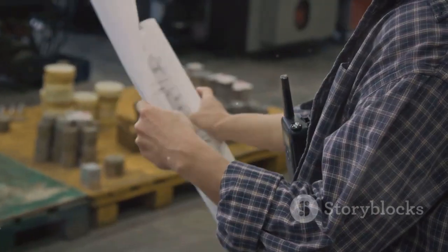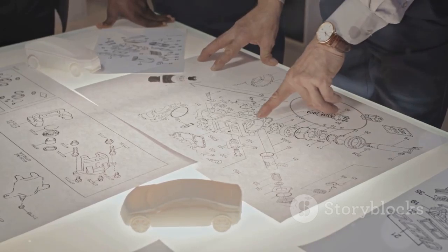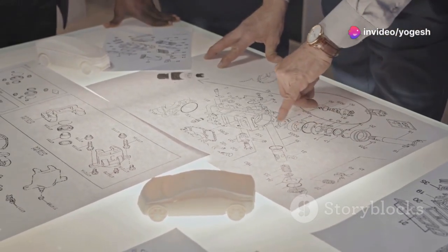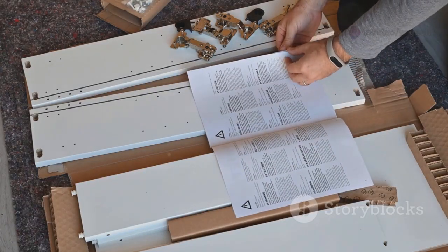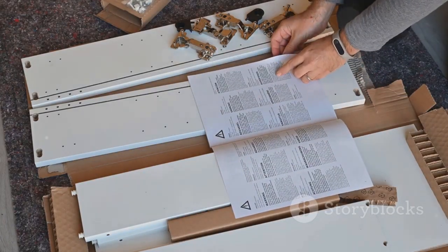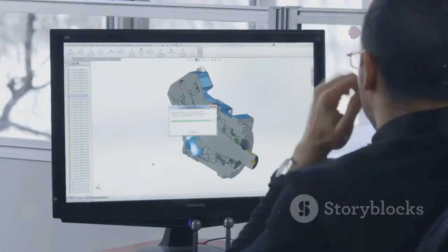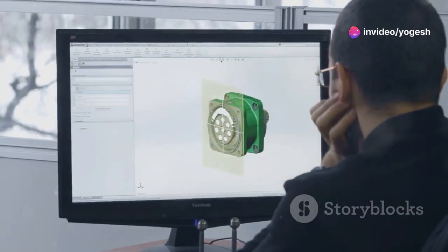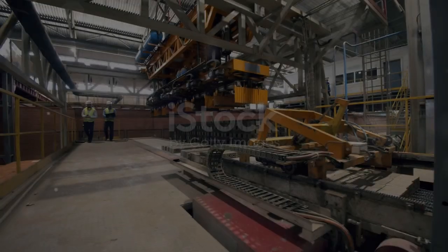For technicians, review the entire drawing set before starting. Check the exploded view, read all stage tables, and verify parts against the bill of materials. Never skip steps or change the order. Each sequence is designed for a reason. Pay attention to notes on torque, lubricants, and sealants. Use all provided views to confirm part orientation and placement. A disciplined approach ensures quality and professionalism.